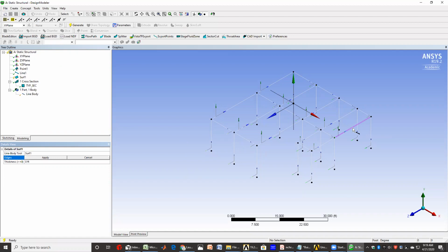It's kind of like a line with 2 dots, that little black sign that I'm highlighting like this. This is important for us because this is basically picking up a line. As we will see, we can also pick up an edge of a surface, and that will be with a different symbol. I want to be picking those edges as lines.